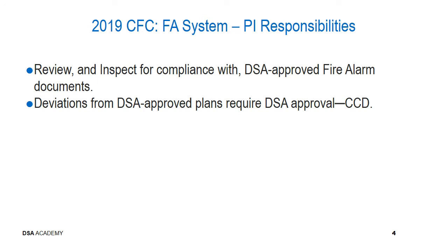When an initiating device, notification appliance, or control relay is deleted, another device, appliance, or control relay on the circuit shall be operated. Hardware modifications or repairs to control equipment must also be tested. Additionally, any modifications to site-specific software must be identified and tested. Copies of site-specific software need to be included in the fire alarm documents cabinet.